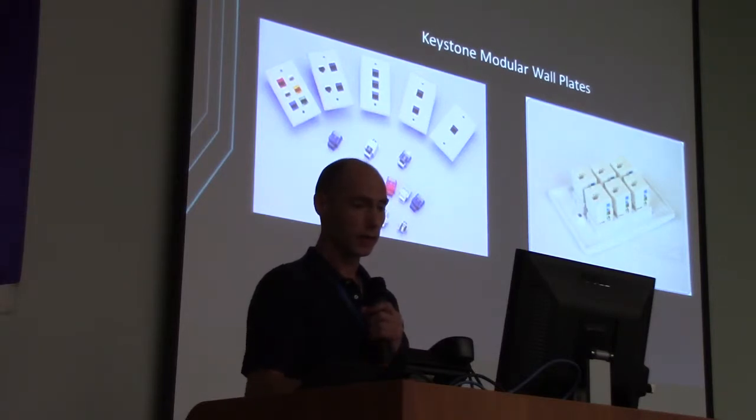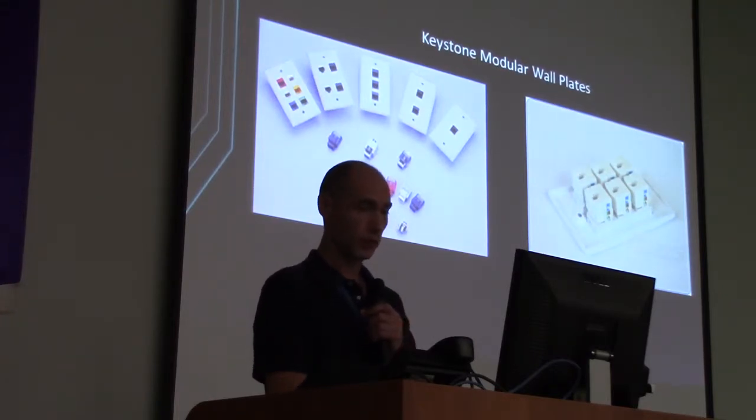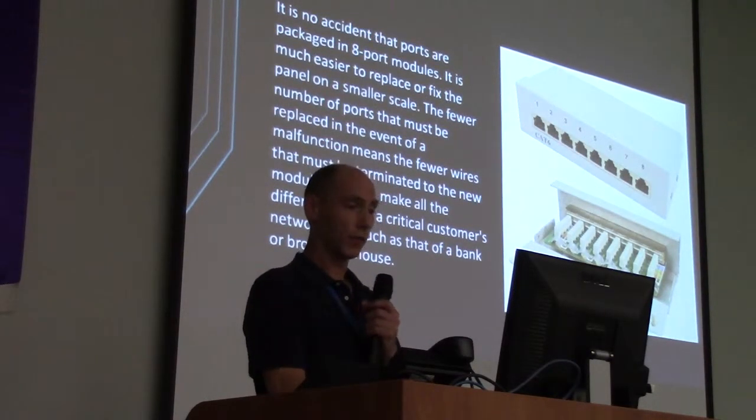That's a picture of the back. They just kind of snap into place after you put the keystone and terminate your wires into the keystone. Then you just snap them into the wall plate and screw the wall plate in and test it. Hopefully it works.